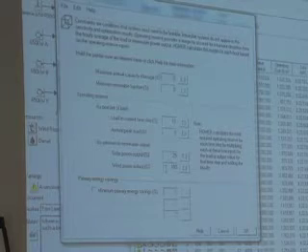Question on that. If a wind turbine, for instance, cuts off at 25 meters per second, whether it's supplying power to the primary load and maybe a secondary dump load, basically by putting 100% there, you're saying that if it is 27 meters per second and the turbine shuts off, you've lost 100% of your wind, and one way or another you have to have that capacity elsewhere in the system fast enough to get the diesel on or whatever. Right, or whatever other resources you have in the system. You just have to have enough capacity to replace it.